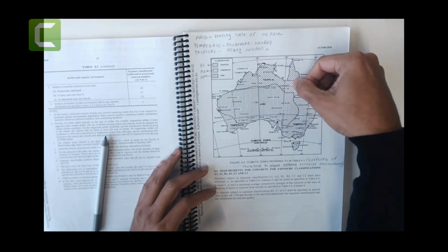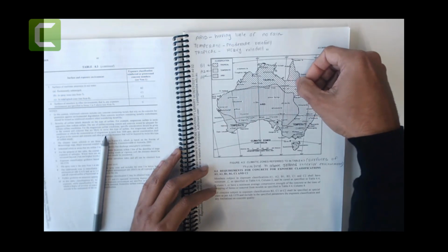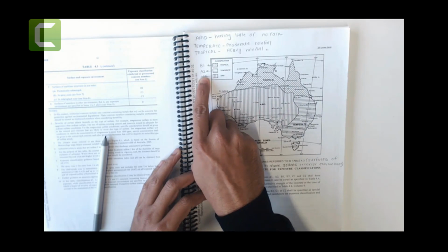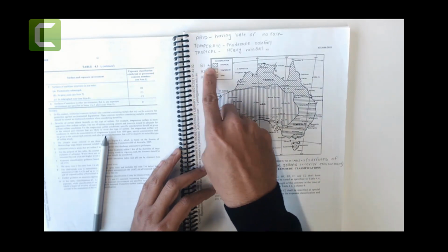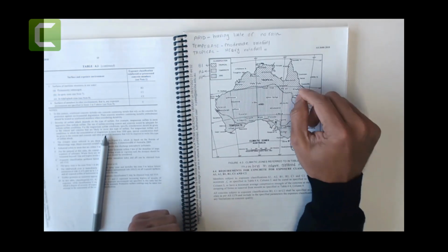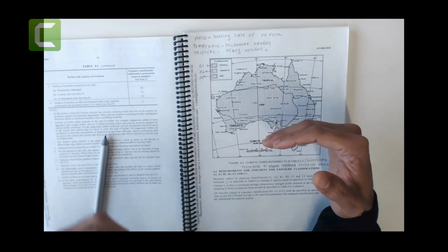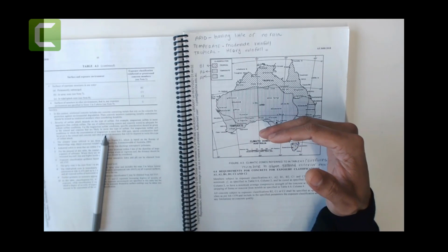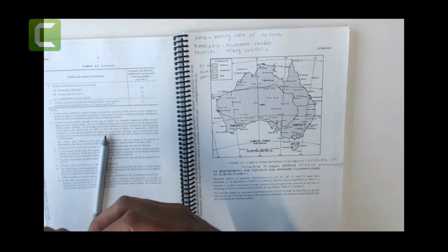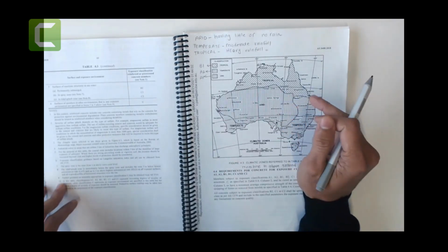North side, like Darwin and Queensland, they have heavy rainfall. So they fall in the tropical weather zone, like a crosshatch. So you have tropical weather. Look at this: this is less severe, this is more severe, most severe. You can see these classifications as well. Because if your concrete is exposed to more rain, it has less life, because concrete doesn't like water. If there is a crack, water goes into the reinforcement and starts corroding, the bond between the reinforcement and concrete is gone, and so on. That's how it starts causing trouble.